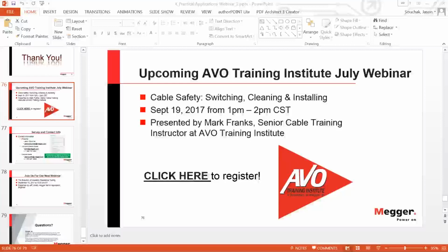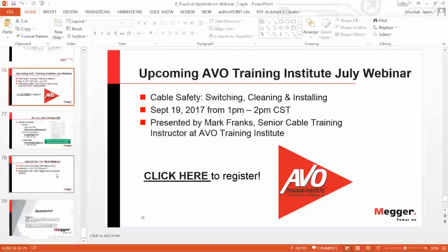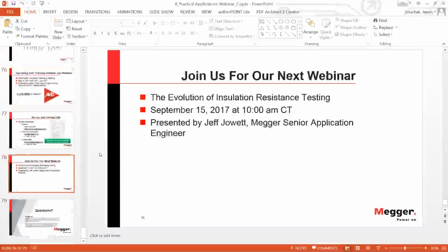The only other thing is, when you have a good tan delta reading, or let's say a tan delta reading that's within the norm, it doesn't really mean, I hate to say, that the cable is a good or bad cable, because it only tells you that the dielectric aging condition of that insulation is still very, very tolerable. That doesn't mean you could not have one spot in there, like Jason was showing. You might have one bad water tree and that's going to blow, right?